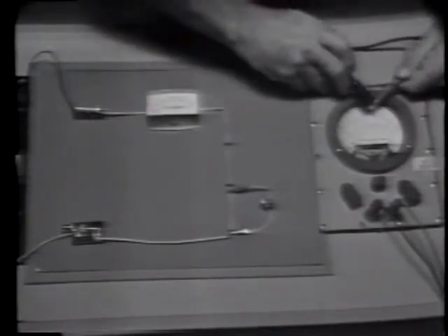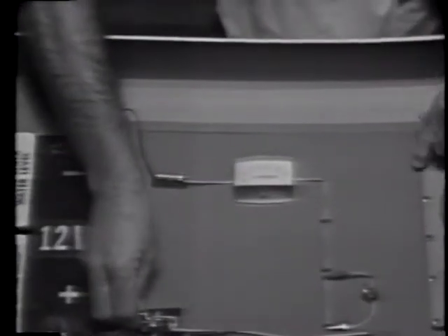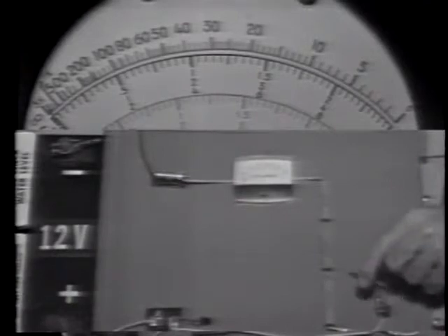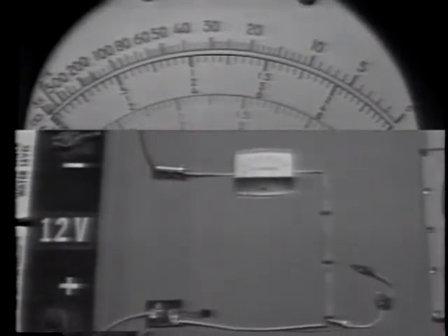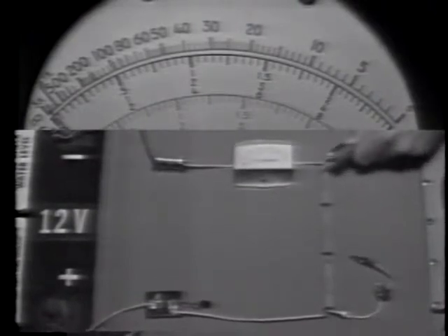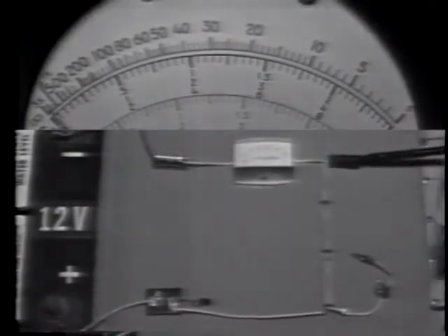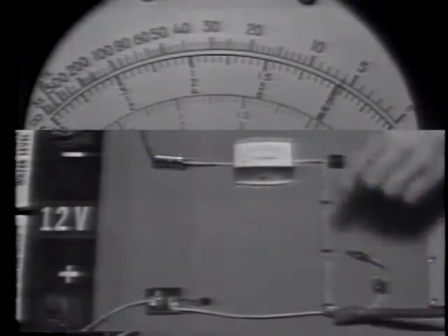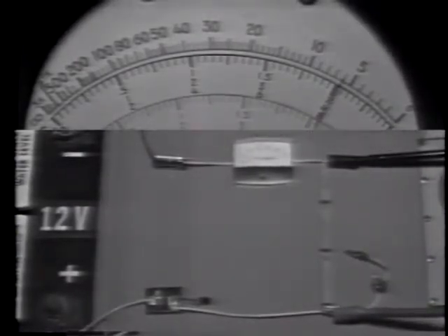And we can verify this by using the ohm meter. So let's go to the PSM6, set the function switch to ohms, and we'll use a range of ohms times 10. Of course, anytime we're using the ohm meter, we must make sure that it's zeroed. And it is. Okay, I'll remove power from the circuit by opening this switch, and I'll take the load device out. Now, let's check the voltage divider resistance first with no load device on the circuit. I'll make the connections here and here. Of course, we're neglecting any meter resistance.